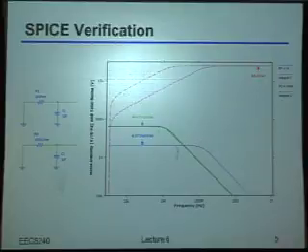If you look at the net area under those 2 curves, which is what this red and purplish line are showing, the integrated noise versus frequency, you'll see that if you integrate from 0 out to infinity, the net noise that you get will be exactly identical. Okay? So this argument, about the noise density changing the same way that the bandwidth does, is one very good way of seeing this.